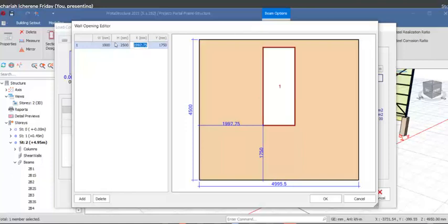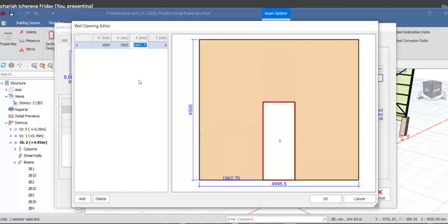So you have that, and then you see the offset, which is the vertical direction of it. You can take it down to 0. You have something of this kind. All right. Then the door width, you can as well change it. Okay, 1,800 as a workshop door width. Just like that. Then the next thing you have to now do is to centralize this. So centralizing this, you have to change this value in the X direction. Having known that this is about 4,000 something, you can just choose 200 right there.